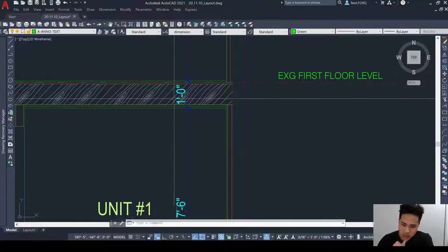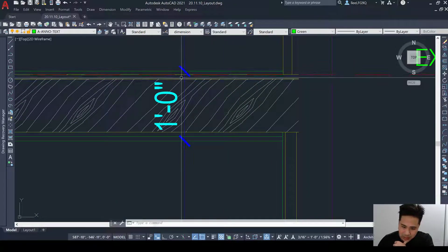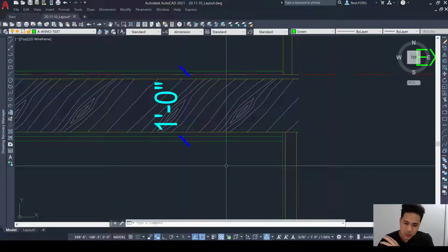And we're just going to use the 12 inches for the plenum height, although it's going to be a little bit less, just because making it just a little bit more to round it off and to simplify the calculations is fine. It's better to use a higher number than rounding it lower, so that we can get a higher load calc and arrive at a more conservative load calculation.